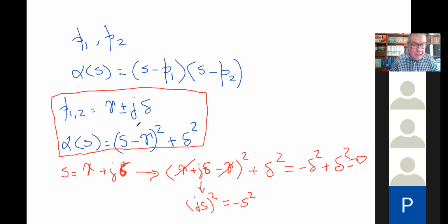If you don't remember this, in general, if you want two poles P1 and P2, it is s minus P1 times s minus P2. That's the way of getting alpha. I should find out what are the convenient poles, and we can discuss it later. The engineering problem is finding the convenient poles. Then the rest is the mathematical problem.